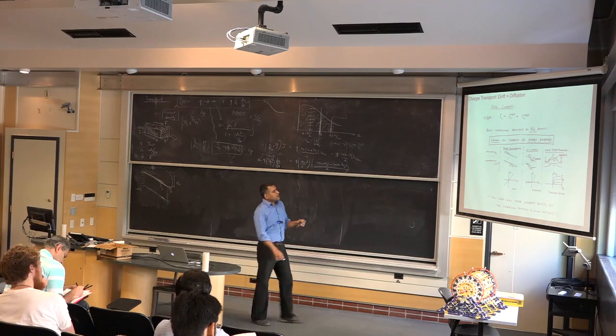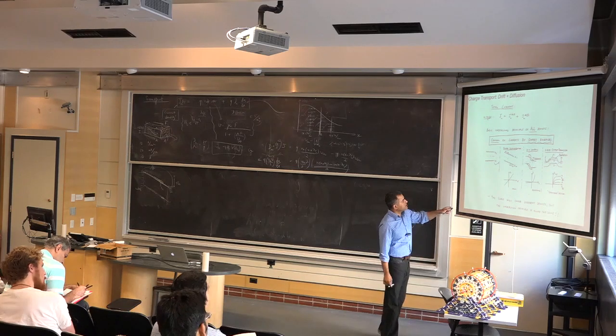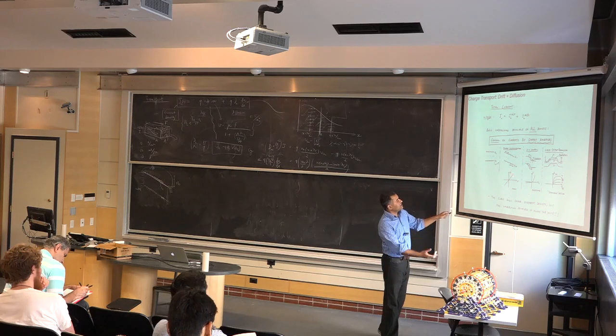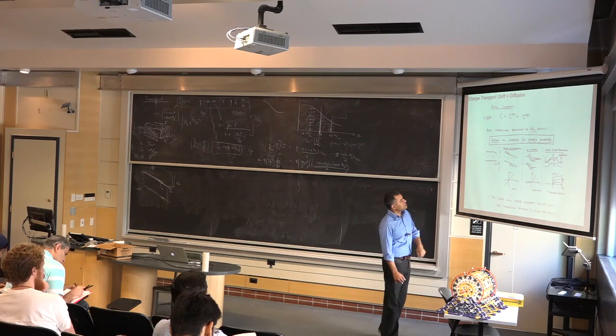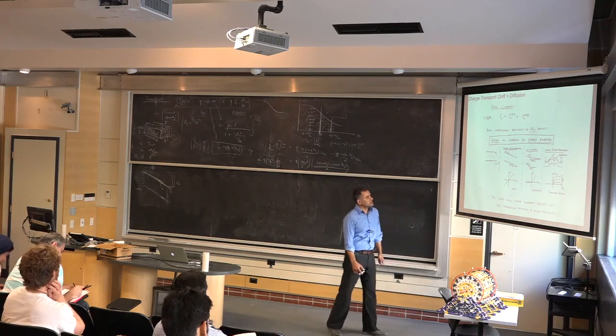Okay, so now this is a uniform field, for example, where the bands bend uniformly, and you will get an ohmic contact then, meaning I versus V would be kind of linear. If you put a barrier like in a PN junction or a Schottky diode, you'll get rectifying current, and we're going to derive those things.